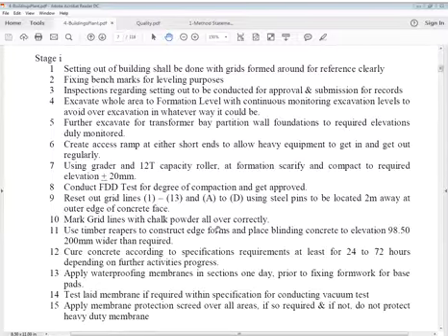So what the height of instrument you get, and you do that reading at whatever point, that's called reduced level of that point, RL we call them, reduced levels. It's not exact levels of GPS, but the referred level, you can say it's difficult to always consider GPS level, so let us say it's only reduced level, RL we call it, which in relation to benchmark we fix work. So fixing benchmarks for leveling purposes.